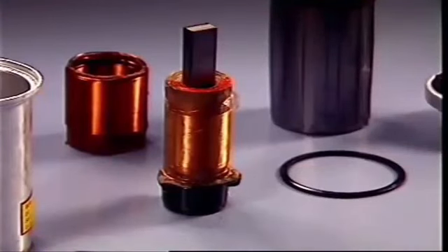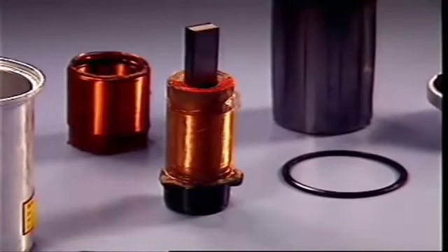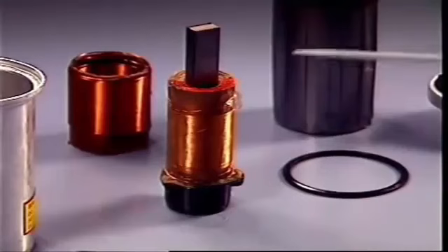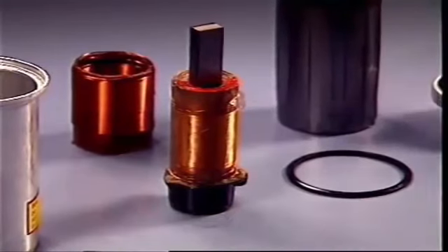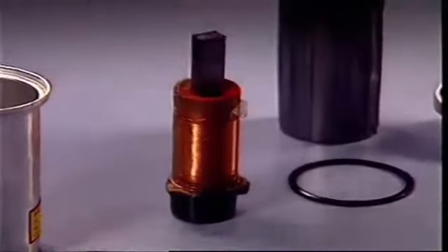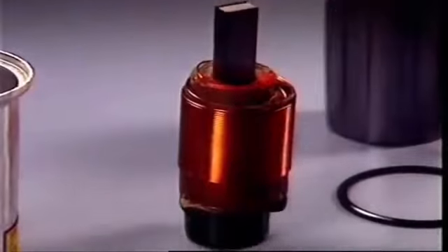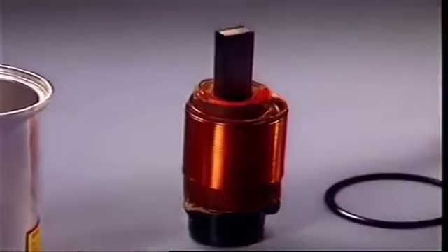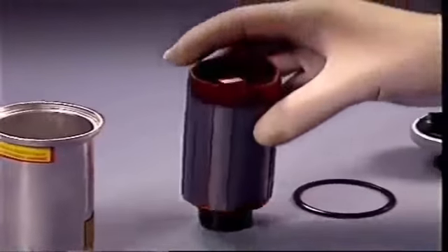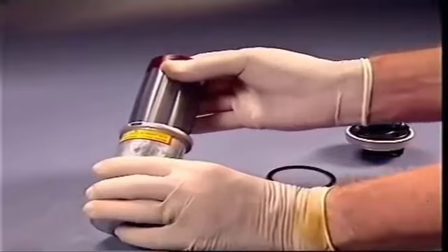The secondary winding, with 15,000 to 30,000 turns of very thin enamelled copper wire, is wound around the core and is insulated from the core by layers of treated insulated paper. The primary winding, with a few hundred turns of much heavier copper wire, is wound on the outside of the secondary. A shield of soft iron surrounds the outer windings, and the complete assembly is inserted into a one-piece steel or aluminium container.